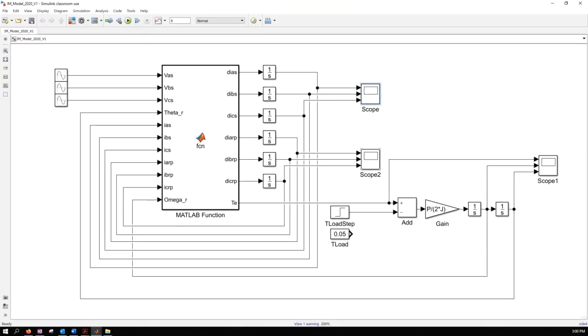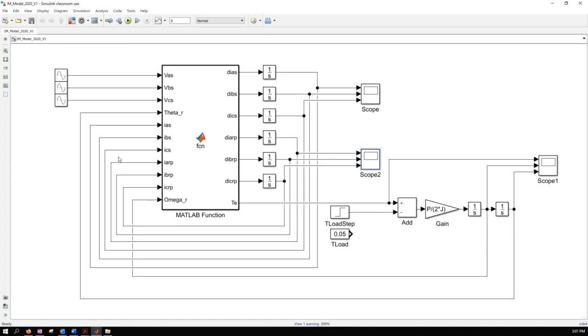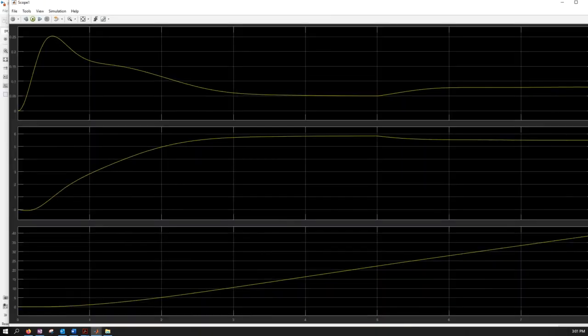Okay, and then these are the rotor currents. If you compare them, see the rotor current frequency is very low. At the startup, it is fast because the motor is not moving, right? Remember, we said the difference between the speed of the rotor and the magnetic field of the stator is what defines the rotor flux frequency, and the amplitude reflects it, right? So as the motor speeds up, the flux frequency drops, and you can see this when we look at the motor speed. See? Very nice. Look at that.